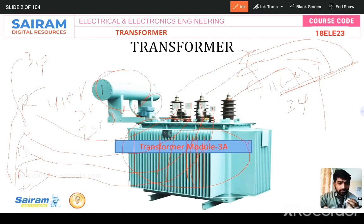If the transformer oil contains dust particles or moisture content, what happens to the transformer? There is a crackling sound, there are flashes. So that's why we have a Buchholz relay, for detecting transformer oil conditions, or if any fault occurs, for example if the transformer windings get damaged, that will be detected by the Buchholz relay.